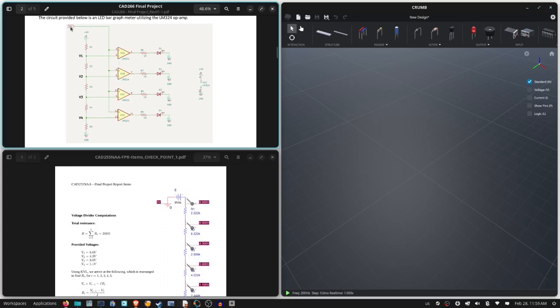And so let's say we feed in 3/5 of 9 volts, and it's just slightly over 3/5 of 9 volts. Because this reference voltage at the inverting input is 3/5 of 9 volts, and we fed in slightly over that, this amplifier will turn on, the output will be high, and the LED will shine.